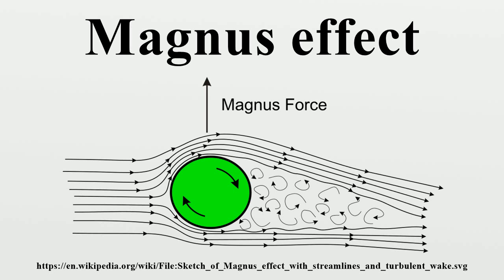On a cylinder, the force due to rotation is known as Kutta-Joukowski lift. It can be analyzed in terms of the vortex produced by rotation. The lift on the cylinder per unit length, F_L, is the product of the velocity, V, the density of the fluid, and the strength of the vortex that is established by the rotation, where the vortex strength is given by the expression in which S is the rotation of the cylinder, omega is the angular velocity of spin of the cylinder, and R is the radius of the cylinder.